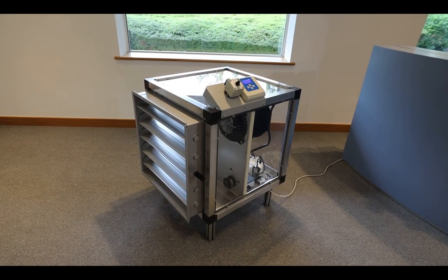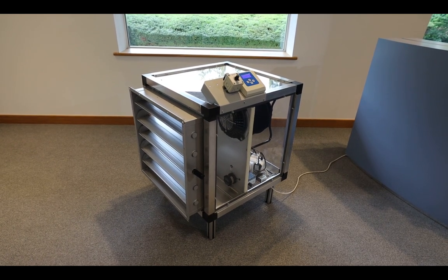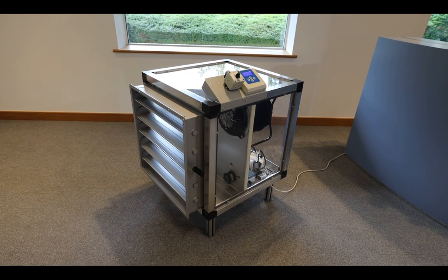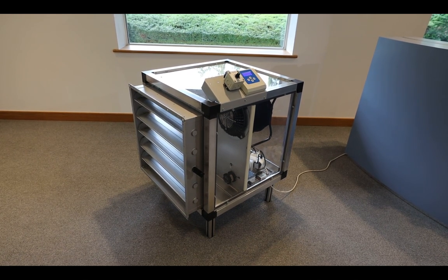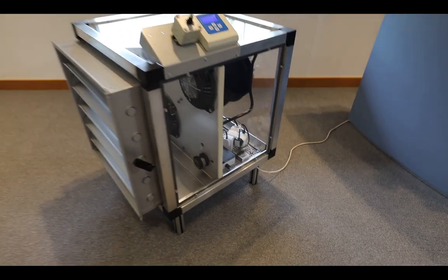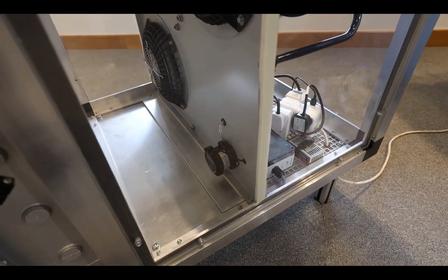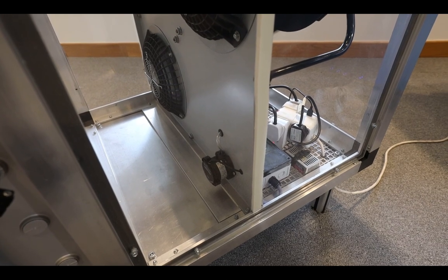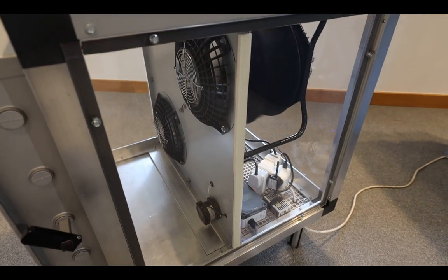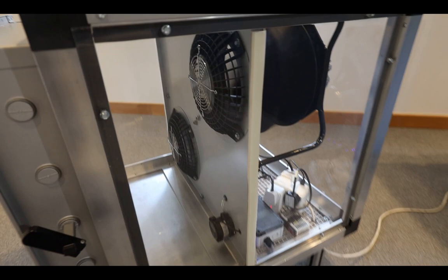This is the smaller of the two units that we're using to demonstrate the functionality of the MDC controller. Installed on the suction side is a variable position louver which we're using to simulate a filter becoming progressively blocked. In the suction side plenum, we're using a pressure transducer of the diaphragm type to measure the pressure difference between the plenum and the pressure tappings on the inlet rings. The fans are the K3G 250 type. They've been fitted with flow grids and finger guards.